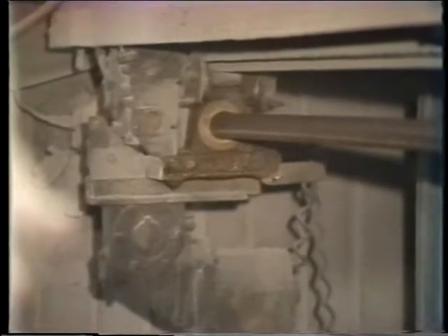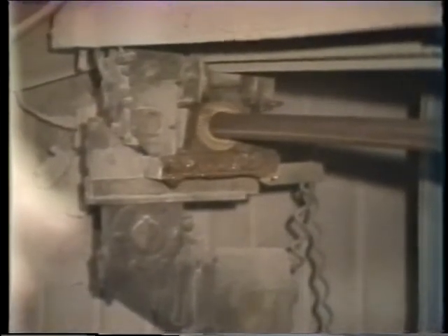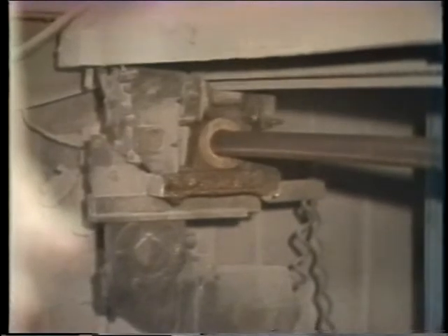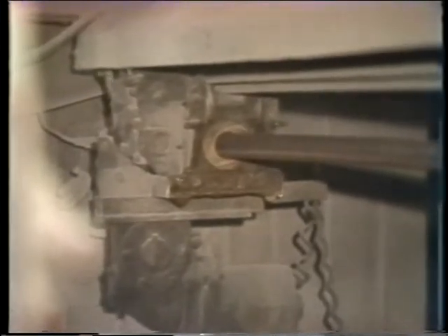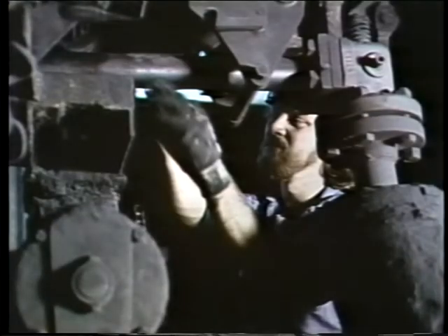Of course, these may not be all you'll have to work on. For details of troubleshooting and in-service maintenance procedures on the components in your facility, you'll need to look up manufacturers' manuals and familiarize yourself with the specific soot blowers you'll be working on. In general, though, let's take an example in one area. Say you found that a soot blower isn't cycling properly. Binding is one cause of a problem with a soot blower cycle. It could be that the tube packing is too tight, and that's causing the soot blower to go through its cycle too slowly. Loosening the gland follower will cure this fairly easily.